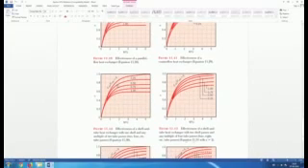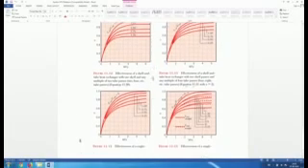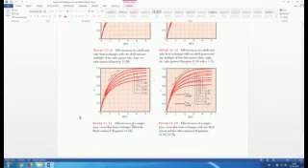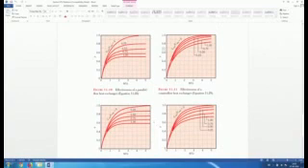And this is the relation which you would get. All these are for a shell and tube heat exchanger with one shell and any multiple of 2 tube passes, that is 2, 4, 6, etc. Again, this is the value for CR equals 0, and this is the value for CR equals 1. The values of epsilon are plotted against NTU, and you also have the shell and tube heat exchanger with 2 shell passes and any multiple of 4 tube passes. So that's the relation which has been provided. This is for the cross flow heat exchanger, which one can see,